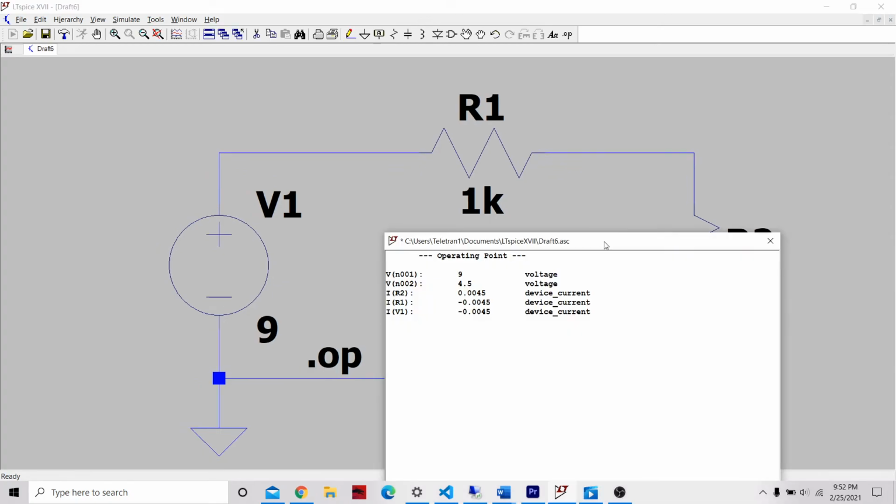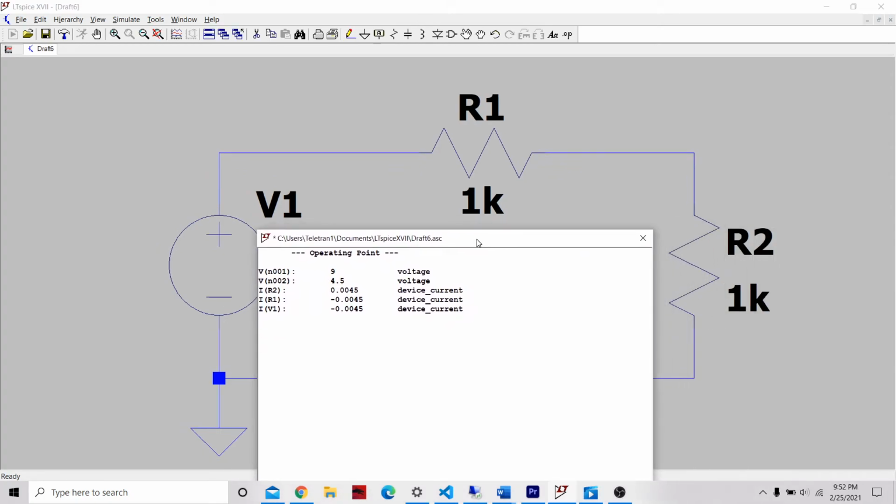So let's look at our voltages here. Notice here we've created a new node, and we're measuring that node from here to ground. So hopefully you've convinced yourself that the voltage across this point is half of what the input voltage is. This is what we call a voltage divider. These are extremely useful, especially for medical electronics, for balancing voltages. That will become apparent later on as we go throughout the semester, but it's kind of cool to think about as well.